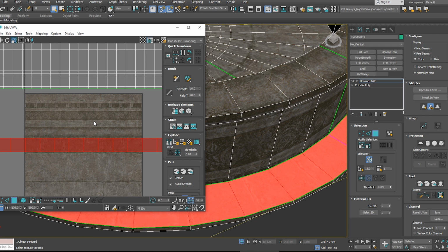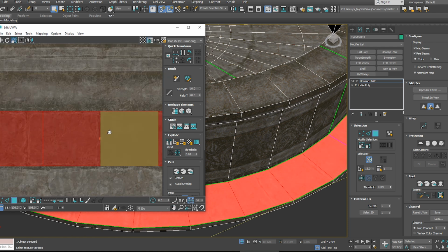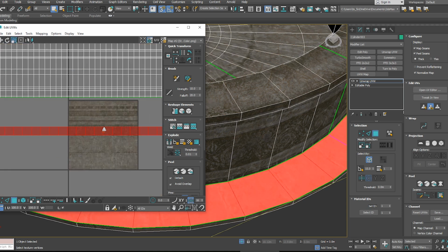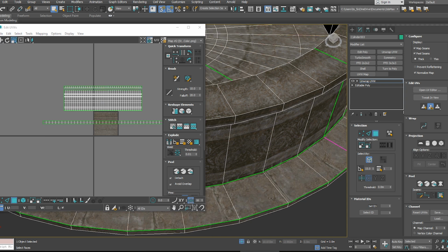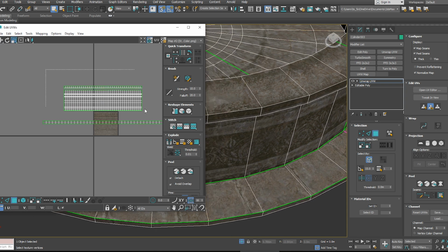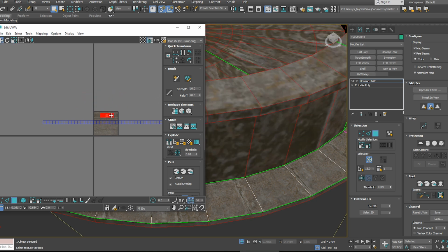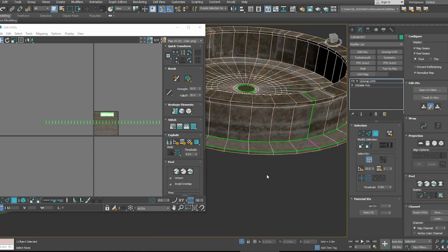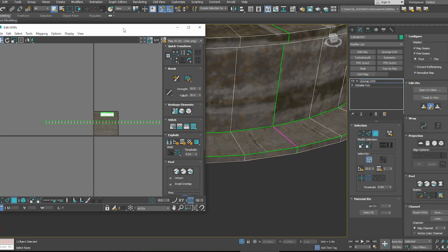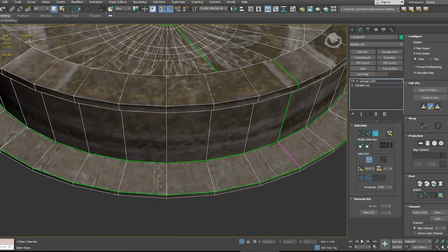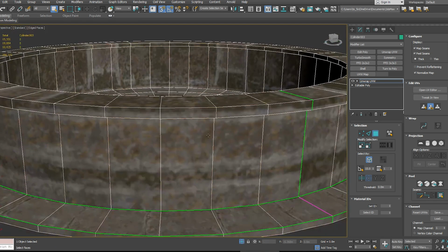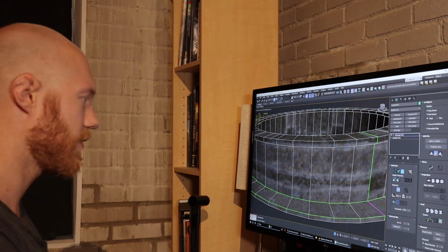So yeah, the texel density is changing a little bit, but it's not that big of a deal. It's never going to be super noticeable. The only time it's going to be really noticeable is, say, I'll give you an exact example right now. Say I have that strip, and then I took all the rest of the UVs, and they were really drastically smaller. When people talk about texel density, this is what you want to avoid. Like you can even see inside of Max, if I get this out of the way, nice crisp texture, horribly stretched, blurry texture because we've scaled the UVs down so much. That's really what you want to avoid in terms of jarring texel density differences.